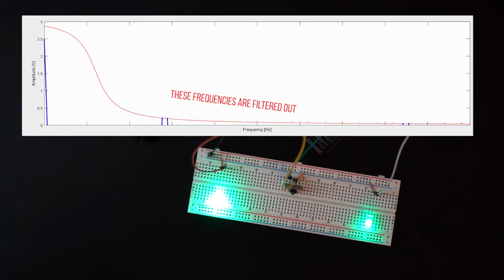Which brings us to the answer for the next question, being why does the light on the right look more dim than the one on the left? Well, right now we're flashing the light on and off at 800 times a second, meaning that we're sending a square wave that cycles 800 times a second to the LED. Now remember the red line in our square wave? That's equal to the average value spike. Because the light is on for just as long as it is off, the average value across one of those cycles is half the brightness. So we detect the light on the right side being half as bright as the one on the left.